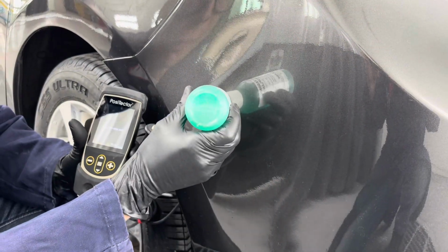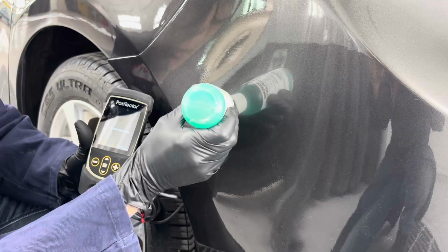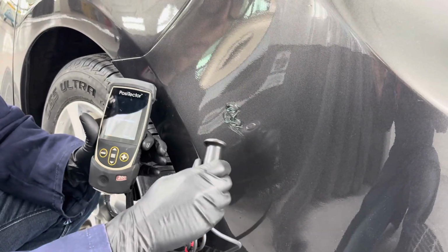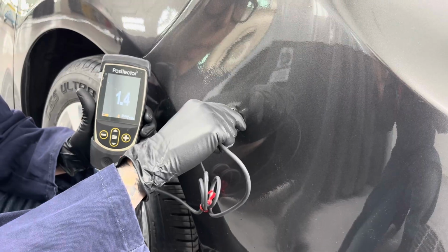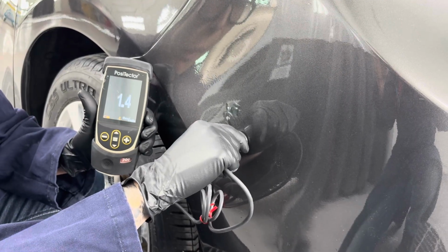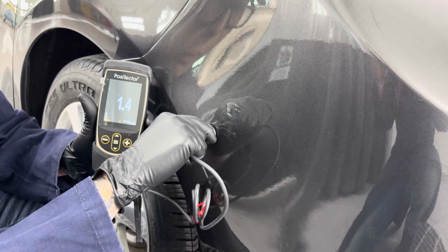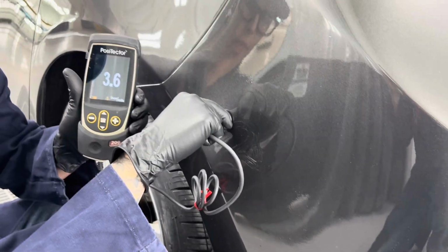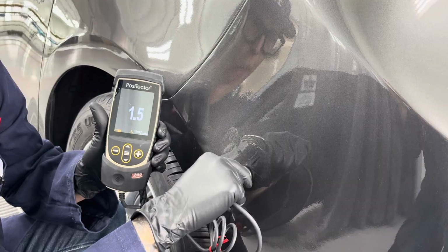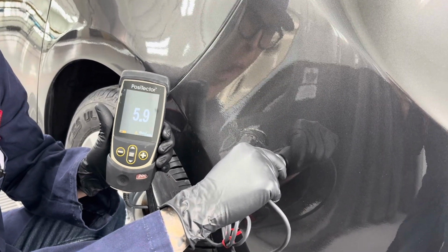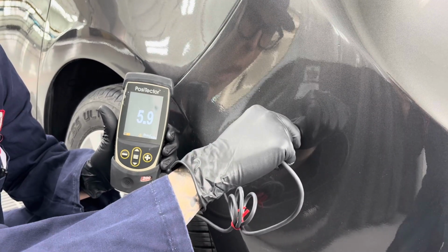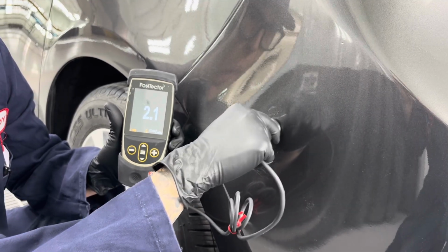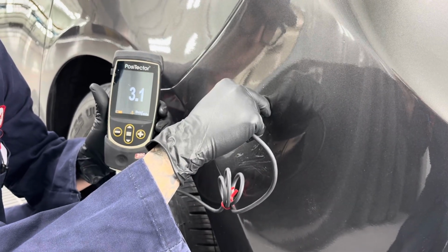When we need to measure paint thickness on non-ferrous panels such as this bumper cover or aluminum and other plastics and composites, we can use this type of mil thickness gauge that uses ultrasonic technology. This tool is able to read through the paint and determine where the substrate is and give us a very accurate reading, very similar to ultrasound using this gel. We can see this bumper has had some repairs done in it before, and it's also had some wet sanding and polishing, which has reduced the mil thickness in a few areas.